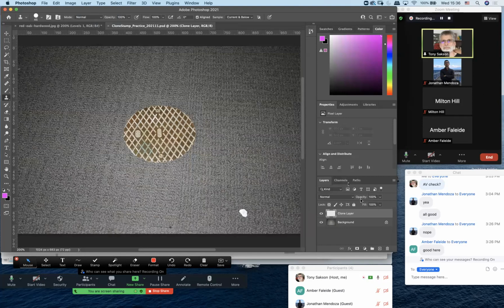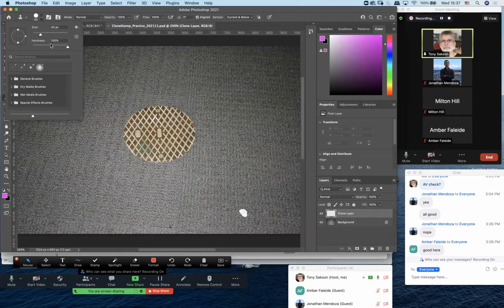All right, so now we're all saved. Got a blank clone layer. I'm actually on that layer because that's what I have selected. So in the clone stamp options across the top, you want to make sure that your brush size is 100%. We do not want soft edge blurry pixels when we start clone stamping. Nothing says, hey, this image has been altered, than fuzzy pixels.